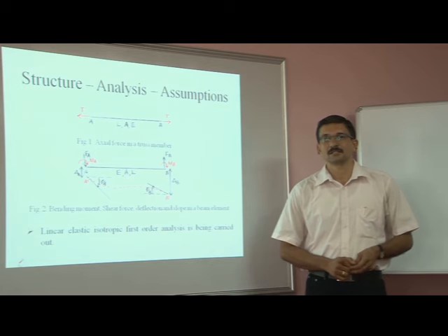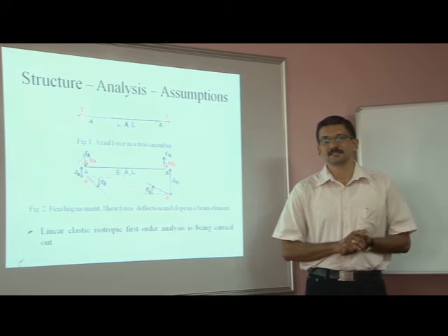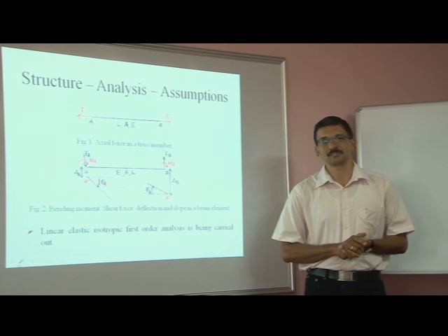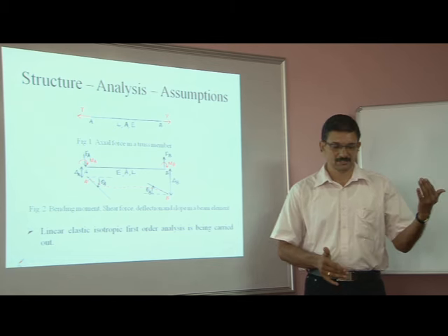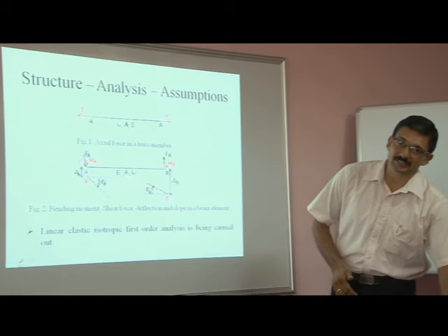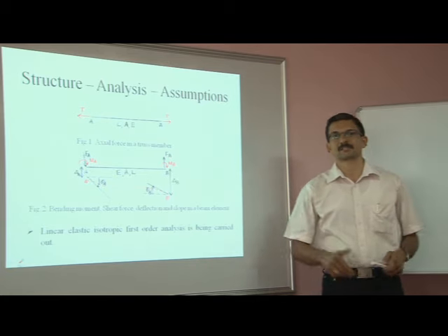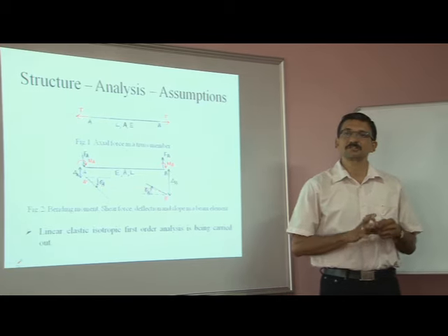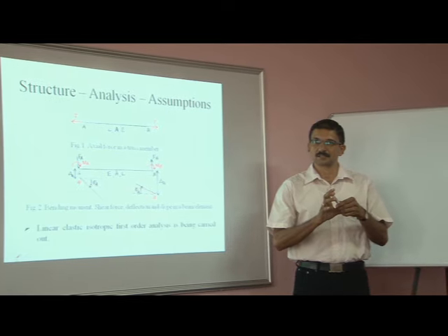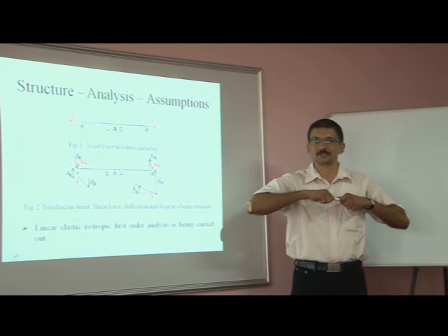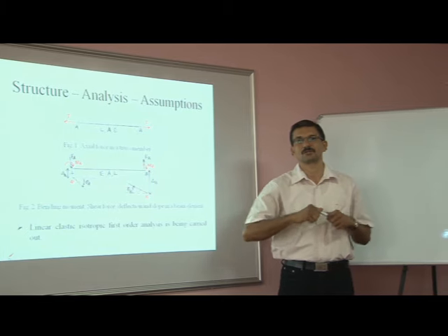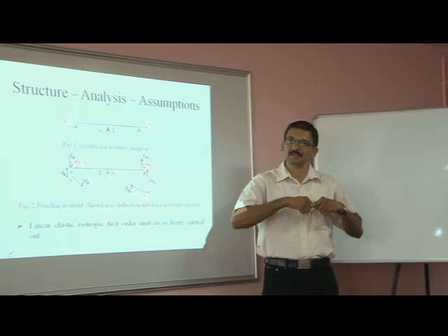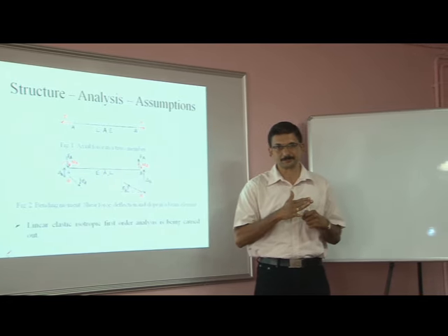Well, the purpose of analysis is to find out the internal forces in a structure. We know from previous knowledge that in a truss structure, which is used as a roof structure, the elements of a truss structure undergo axial forces along the longitudinal centroidal axis of such members. They can be tensile force or compressive force.